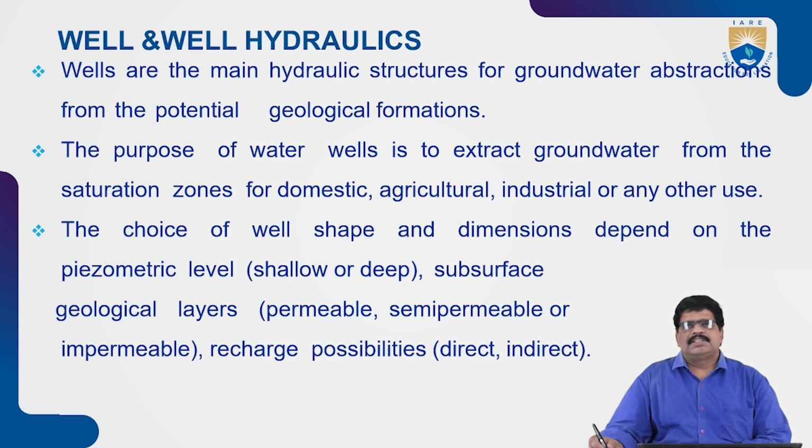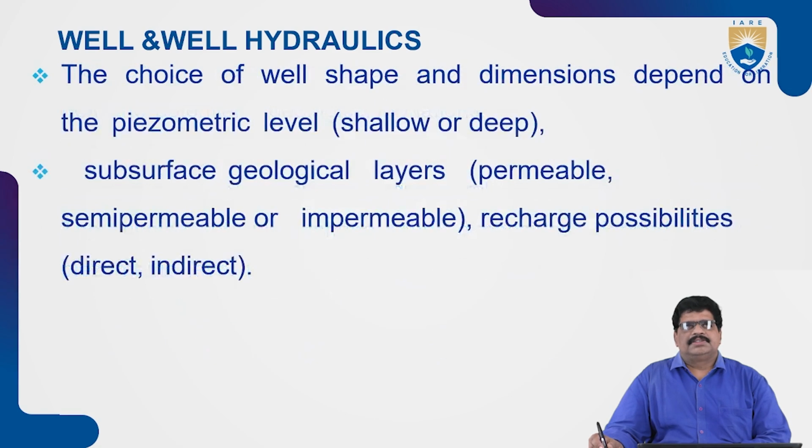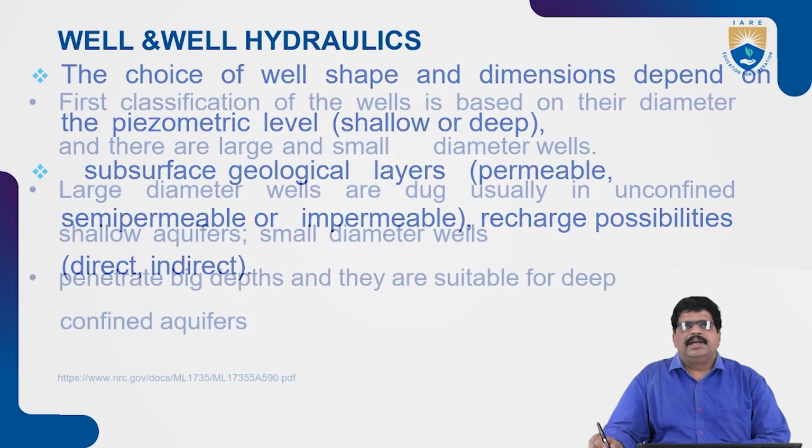The choice of the well shape and dimensions depends upon the piezometric levels and whether the layers are permeable, semi-permeable or impermeable, and on the recharge possibilities, whether direct or indirect methods. The choice of the well dimensions depends on the piezometric level, whether shallow or deep levels, the subsurface geological layers being permeable, semi-permeable or impermeable, and the recharge possibilities, direct or indirect.